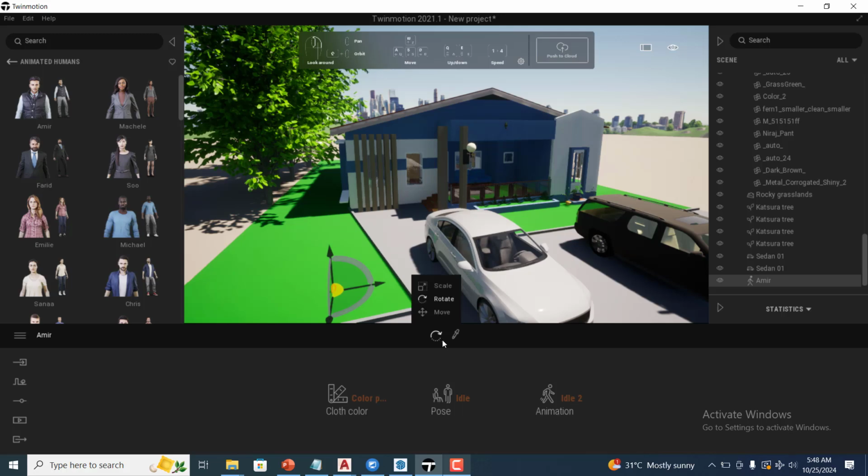So you can see it's on rotate. If I want to change this to scale, I will just type 7. Once I type 7, automatically it has changed to scale. If I click on that particular character, you can see it's bringing up a number for me to type in. I can rescale this to however I want it. So let me make this scale 10, right?